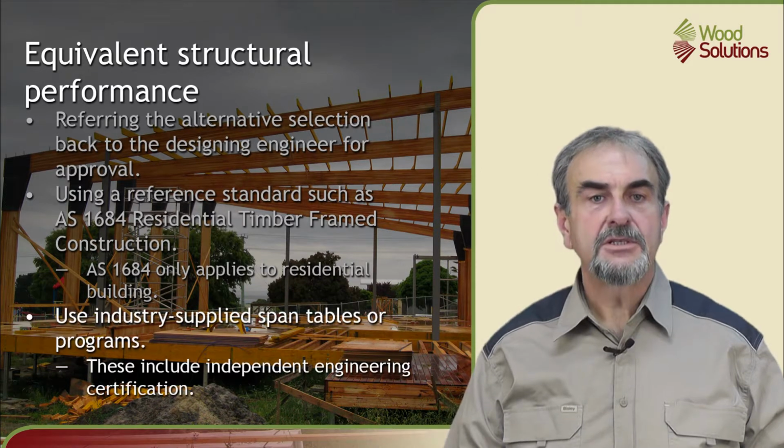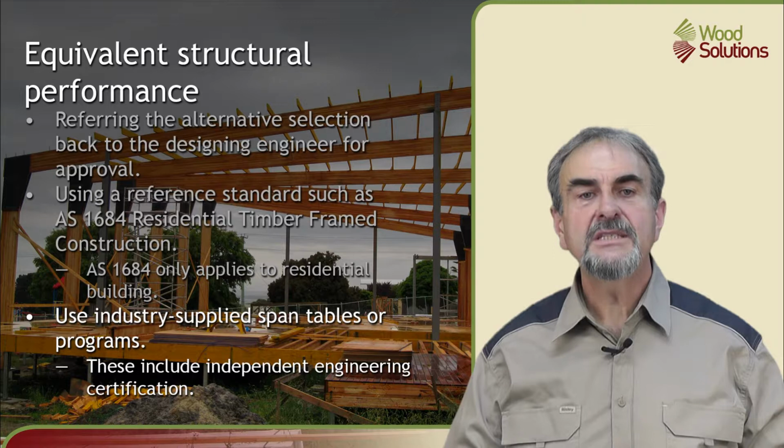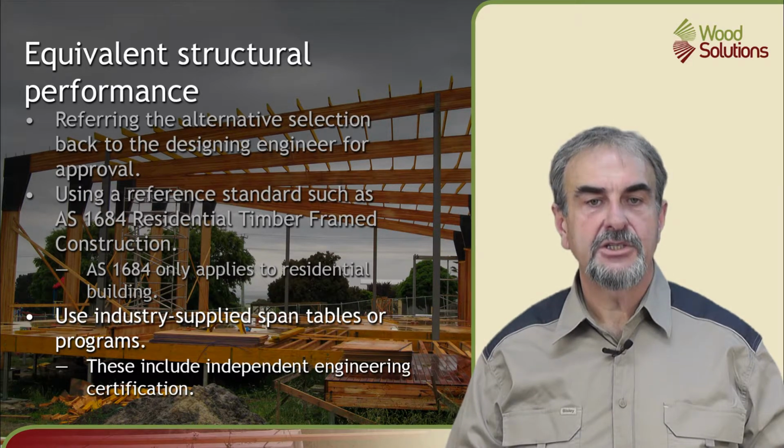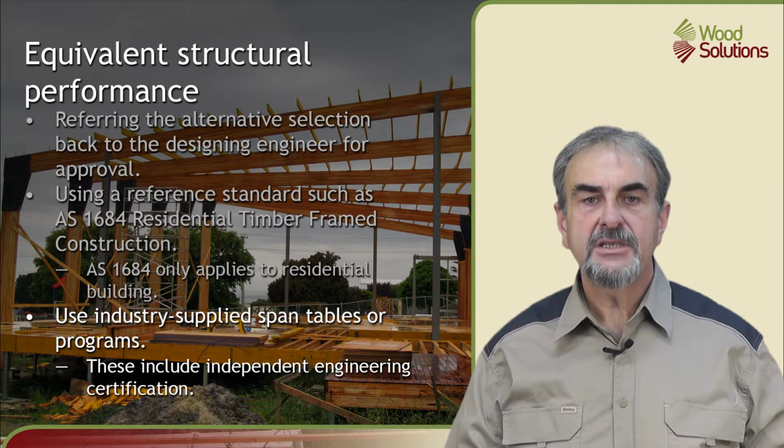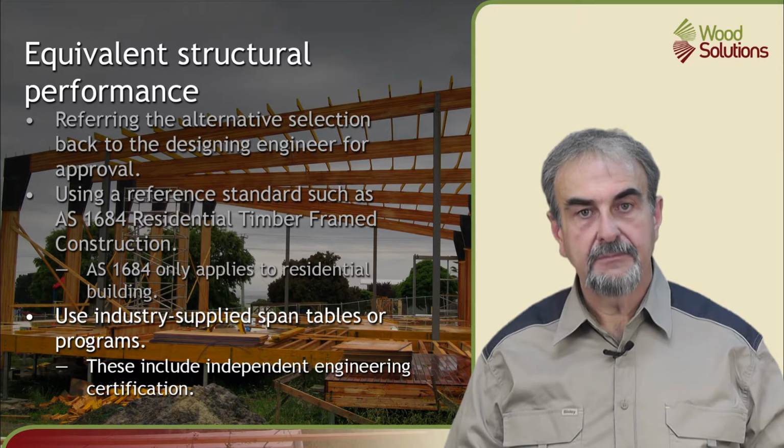The last option is to use the industry supplied span tables or programs. These will always have independent engineering certification. Using AS 1684 and industry supplied span tables and programs requires skill and a workable understanding of building types and load requirements. They should only be used after suitable training.